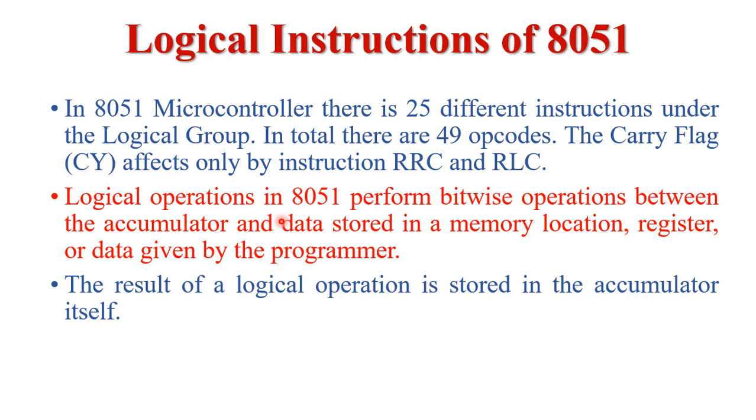So by using this instruction, we perform some basic logical operations like AND operation, OR operation, XOR operation, NOT operation, etc. These logical operations in the 8051 microcontroller perform bitwise operations between the accumulator data and data stored in a particular memory location, data stored in a particular register, or data given by the programmer. And the result of the logical operation is always stored in the accumulator register.